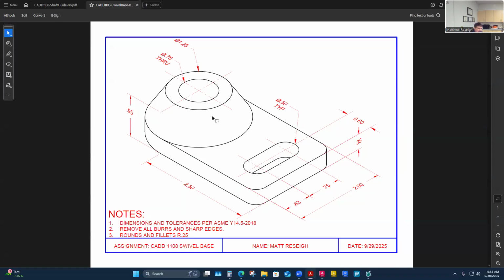And then I'm going to have to do this cone-shaped feature. And that might be, I don't know, kind of tricky to figure out, or easier to figure out in the top view and project down maybe. So, it doesn't have a base diameter, but it really does. It's the same diameter. It's 2. So I probably can draw it in the front view. Potentially. This might be one where you draw the top view stuff first and then drop it down.